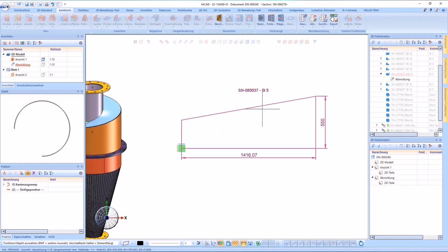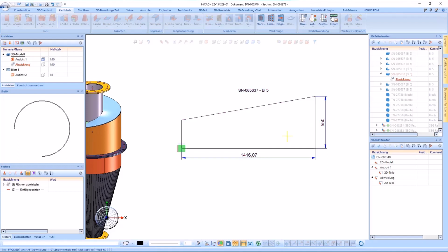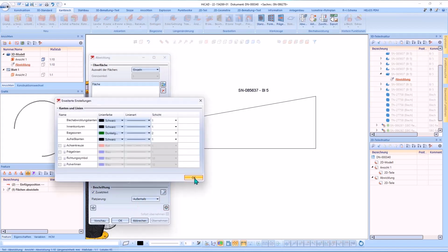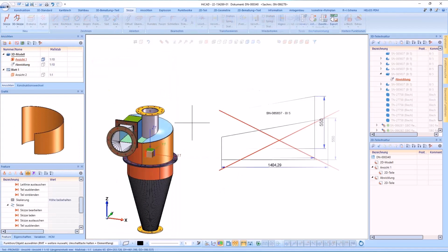The big advantage of the development is the subsequent changeability. Similar to sheet metals, the development can be changed via the context menu. So you can subsequently change the sheet thickness, switch the dimension on and off, edit the additional text or its position, and set the line color. The set configuration can also be saved as a favorite and used for new processing.